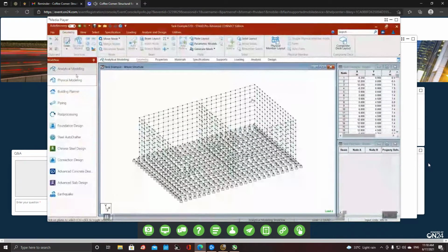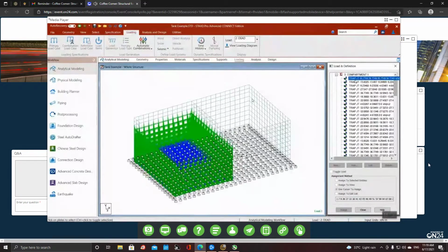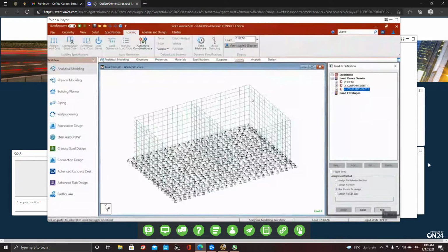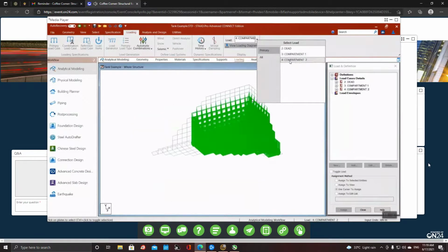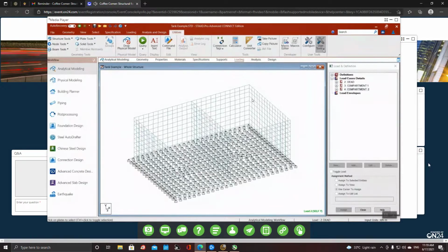Okay, so now we have these 3 load cases. Now all we need to do is generate the combinations, but let's verify the 3 load cases first, okay? Let's view the loads. You can see the compartment loads and the water loads in both the compartments, and the springs generated in the mat, in the slab. It's all done automatically in one wizard.